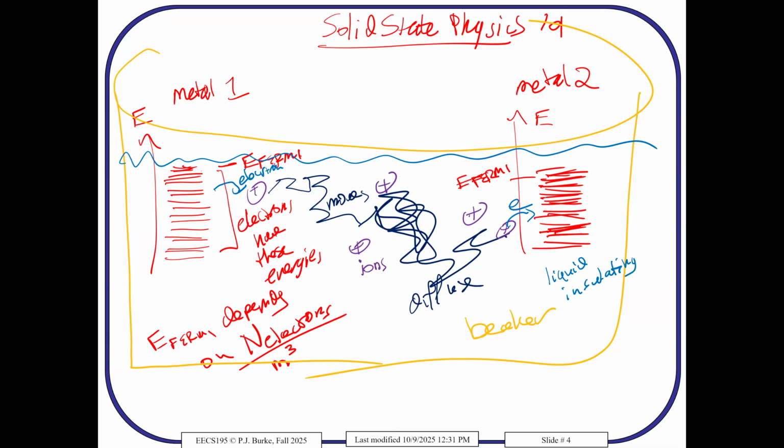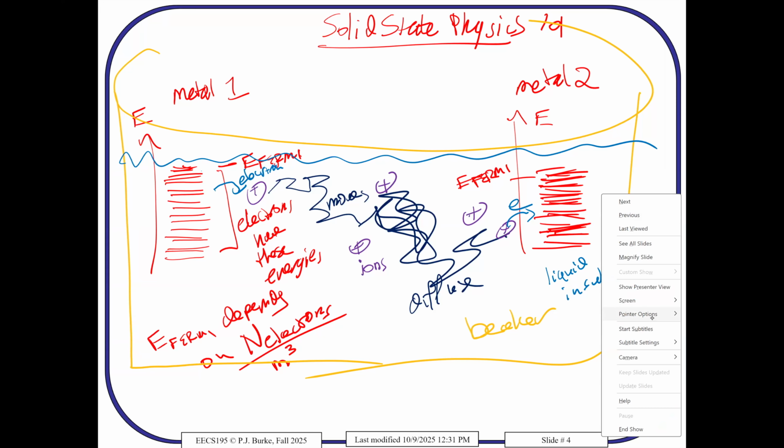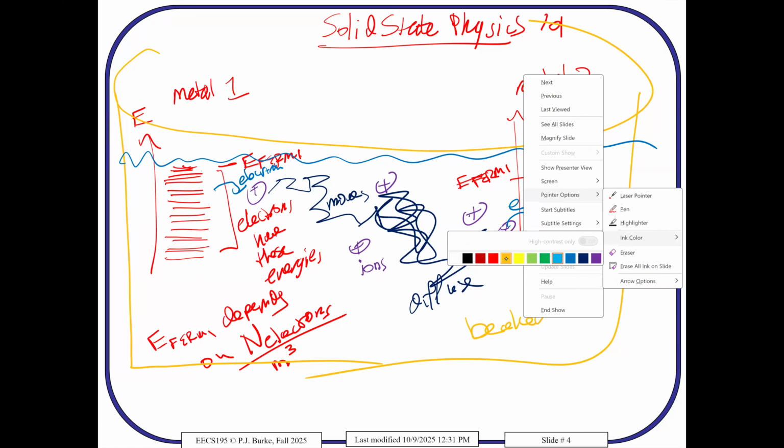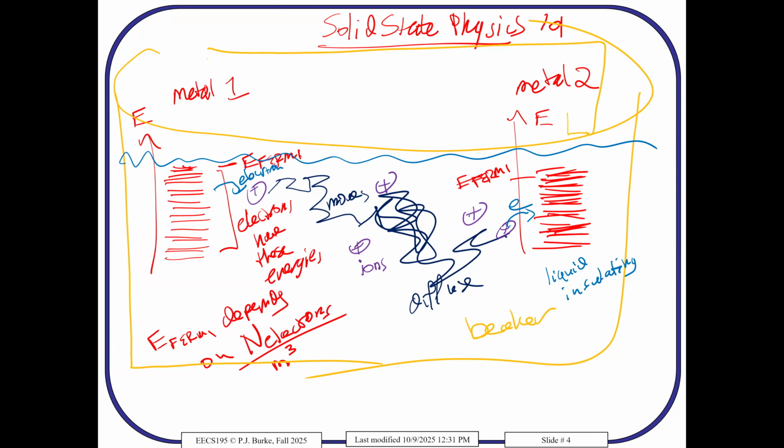Eventually, the electrons can stop there, and then the voltage and the current stop, or you could put a wire. Let's make the wire, and put a resistor here. So those electrons that get brought from one side to the other will go up through the wire, through the resistor, and go back to the original electrode. One's called the cathode, one's called the anode. That closes the circuit, and current can flow. So that's all that a battery is from a scientific point of view.